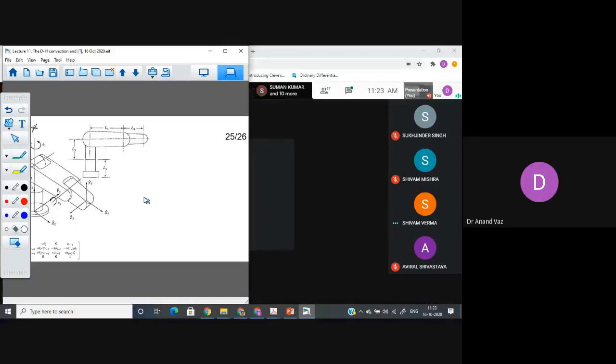Any other query? Sir, is it necessary for each joint to have a single degree of freedom? It is not necessary, but it simplifies things. It helps us obtain the transformations in a simple manner. You can have more than one degree of freedom, for example, a spherical joint. It has more than one degree of freedom, right? It can be realized using a combination of two revolute joints. Do you agree? Yes, sir.